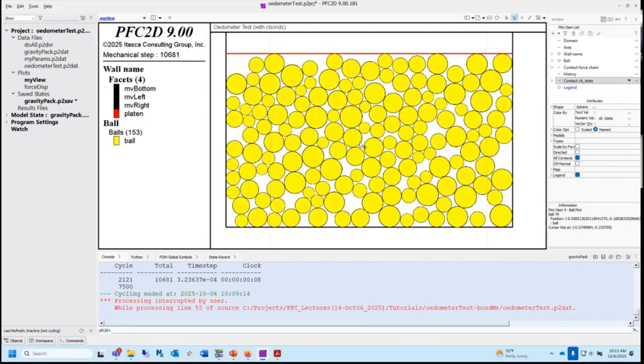And so what we're going to find with this material modeling support package is that this is going to be a key parameter. It's going to implement a packing procedure that isotropically compacts the system until it reaches the pressure you tell it to. If you make the pressure small, it'll pack it to a small pressure and then put in bonds.